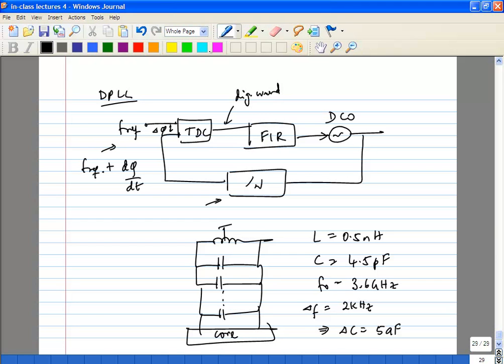What will happen is, if you give something around DC, some low frequency variation, that gets transferred to around F0. Anything which is slow enough will not be filtered out by the loop filter, in the analog or the digital case. That will end up at the control voltage, which means the VCO phase and frequency will change slowly, and at the output you can get a very nicely modulated waveform. That is quite often used in polar modulation or phase modulation.